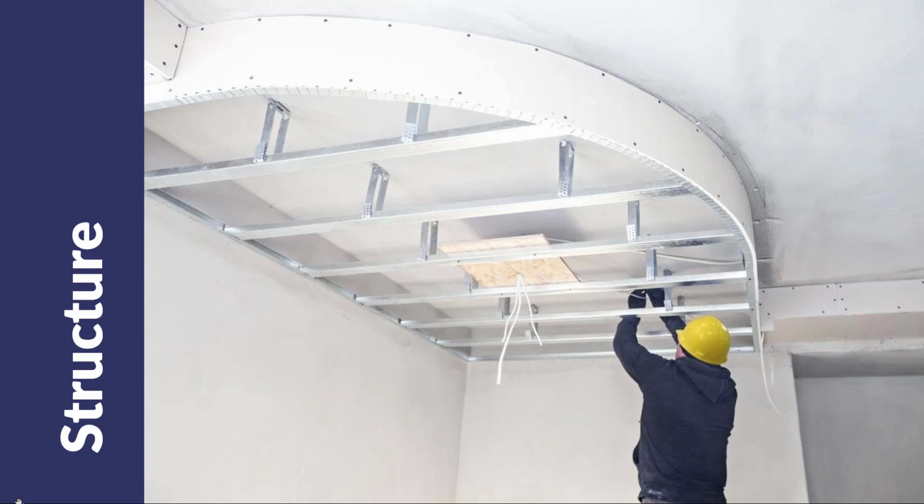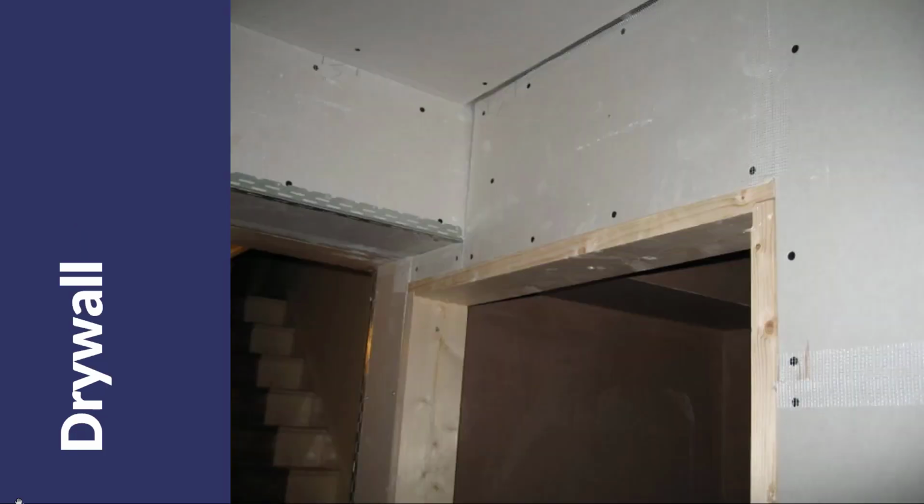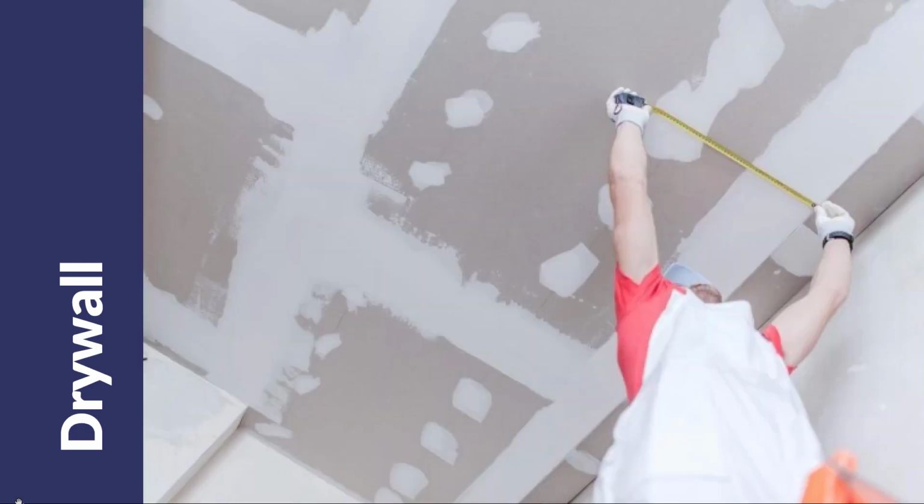So when we think about the structure of a ceiling, in this case we are seeing a soffit, so a dropped portion of a ceiling that's built to be maybe about 12 inches lower. We're really thinking about a similar system to how the walls are built in some sense. So there is a structure behind what you're seeing in a space. So on top of that system, on top of either the wood or metal studs, again, like we have in the walls, we have drywall very often.